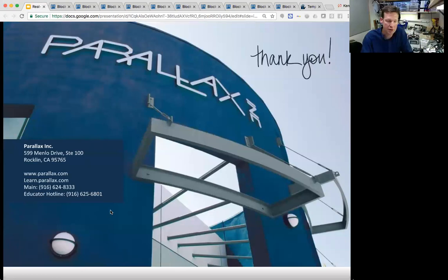And I should point out, too, for anyone hanging around, Wayne spends days with the basics, that is reading push buttons and LEDs. I've seen a number of instructors that do this, and I really advocate it. It's really exciting to get into all the cool stuff, but until you really understand timing in a microcontroller and what's happening, it's harder. You won't know why things fall apart when you try to advance.